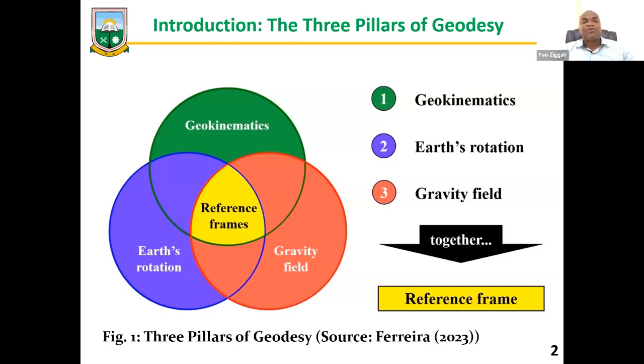In the same way, if we want to mine the minerals found within the in-situ rock, even after blasting, the surveyor needs to set out the ore block for the mine operations department to carry out mining. When you go into road construction, we still need the surveyors to be there, because you first need to understand the topography before you can even do the design. When it comes to building, it's the same. We do the topographic survey and supply it to the architect so that he can orient the building design to suit the topography.